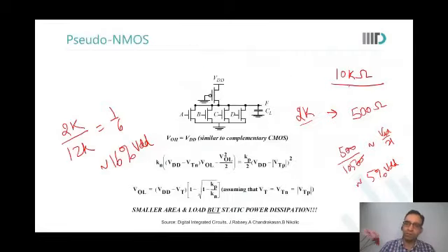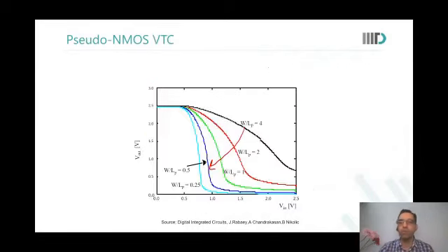You propose what number you would want to use. Let us use that. I have no problem. Let us find out with that number. Tell me. So if we use 2K for the PMOS also? Yes, sir. Let us use 2K for the PMOS. Then what happens when all four inputs are 1? Okay. And it will be the same 500. So output will be then at VDD by 4. Yes, sir. Okay. Now let us say only one input is 1. Then it will be, that will not work for you. Okay.